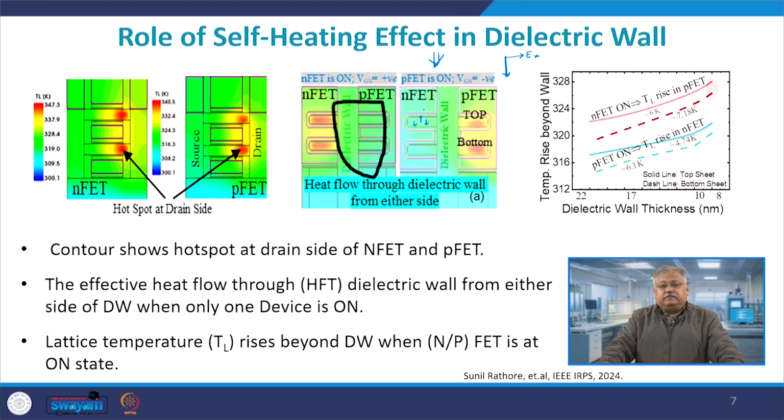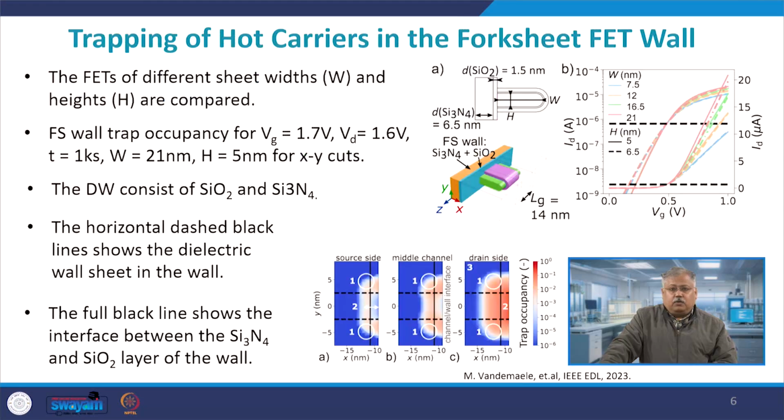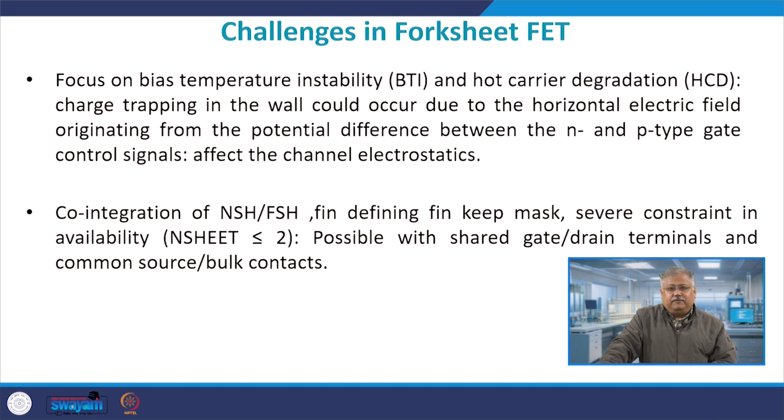But please understand, this is basically an interface with silicon dioxide. So there will be heavy scattering, mobility reduction, and so on and so forth. The electric field which is longitudinal in direction, or which will be going inside the plane of the screen, will result in the movement of these carriers across the channel length, right? Across these dimensions of the channel length. Now these two will result in a large amount of hot carrier effects. Now why is it so?